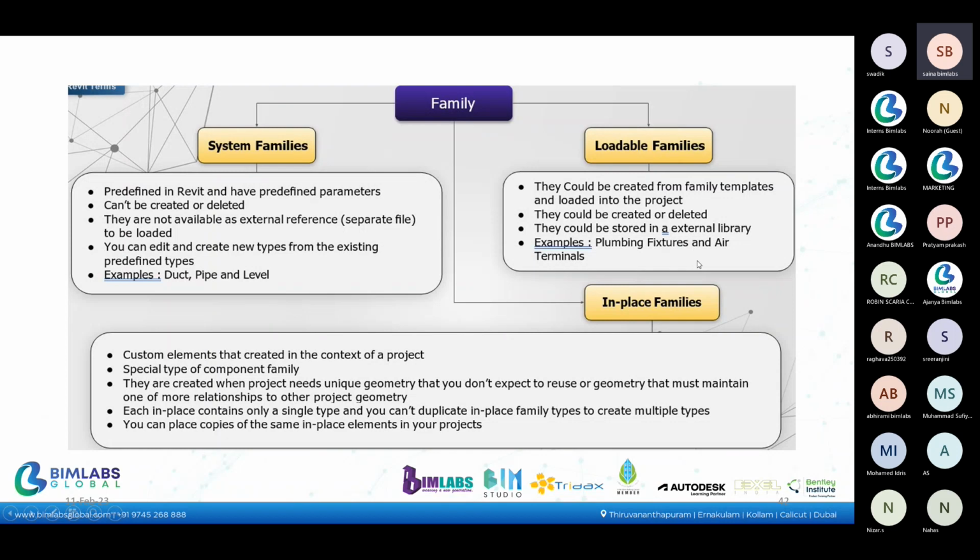Next one is loadable family. Loadable family can be created from family templates and loaded into projects. I already said, if you want to create a door with our own design, we can create it separately and we can load it into our project. That door will come under the door loadable family. Not only the door, windows, furniture, ducts, plumbing fixtures, etc. come under the loadable family.